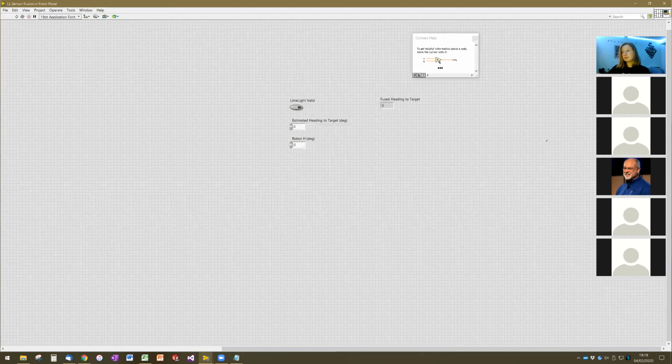And we will still want to have the same capabilities that we had before. Right now, things may change with the new design, but right now, the shooter spins up to a different speed based off of its distance from the target. We would like it to start spinning up to approximately the correct speed as soon as we enter auto targeting mode, even if we aren't facing the target. So that initial spin up might be based off of the distance estimate from the robot location, and then the final target speed for the real shooter is going to be based off of the LiDAR information. And so we need a way to combine that.